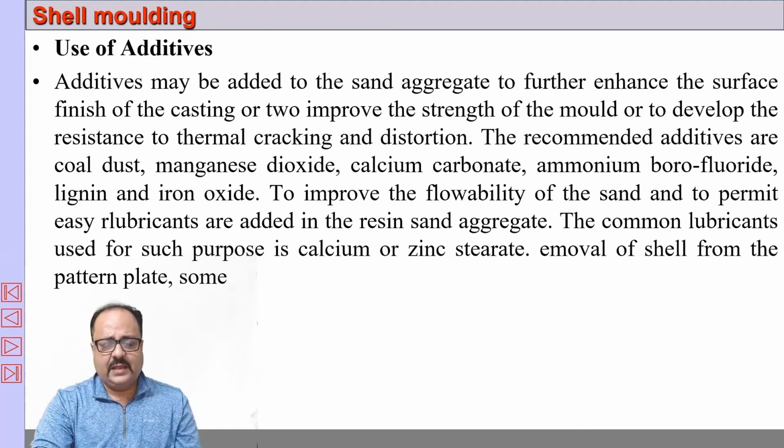Various additives like coal dust, manganese dioxide, calcium carbonate, ammonium borofluoride, lignin, iron oxide, etc. are used. And we also use certain kinds of lubricant so that the flowability of the sand increases. This is basically zinc stearate or calcium stearate.